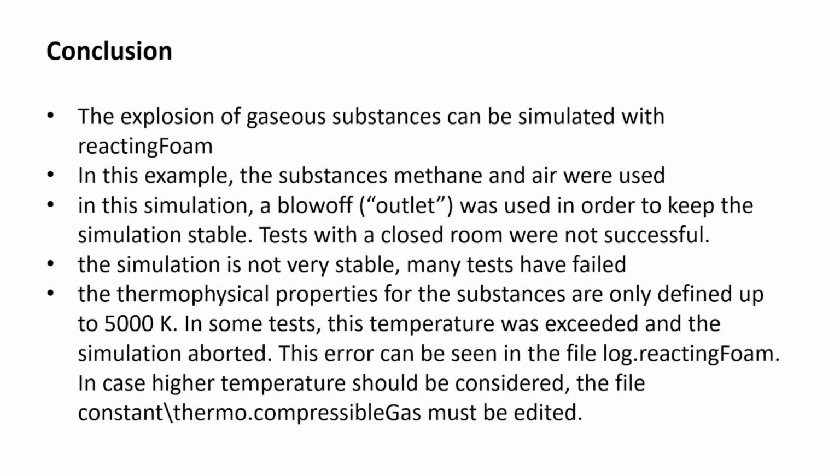Let's come to the conclusions. So first conclusion is the explosion of gaseous substances can be simulated with reactingFoam. In this example, the substances methane and air were used. In this simulation, a blow-off was used in order to keep the simulation stable. Tests with closed rooms were not successful. The simulation is not very stable.